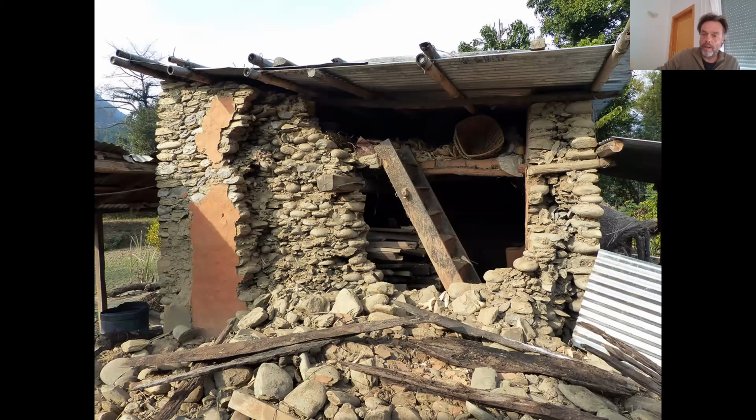Now, what you see here is one of the reasons why these houses did collapse. First of all, you see very round boulders here, coming from the river. Based on gravity, you already see the bulging of the wall. Those stones are already being pushed out. So imagine then what happens after an earthquake. This is done with mud mortar. I'm going to show you in more detail in the next half hour what happened here. But the problem is this.